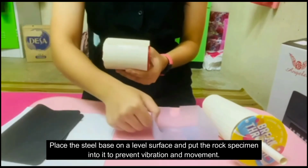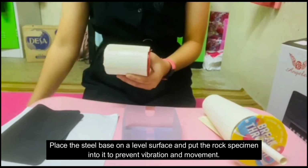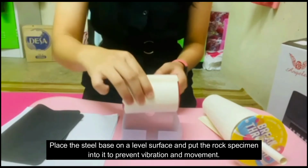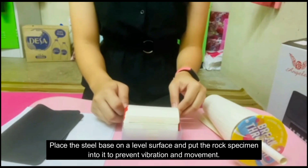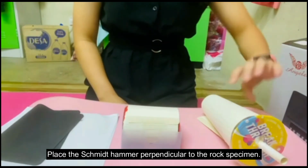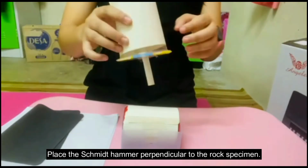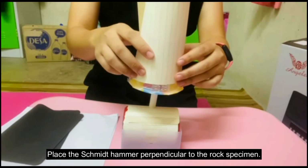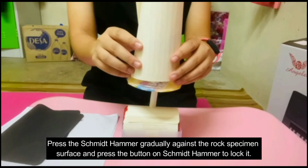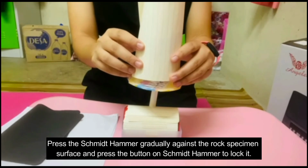Then we place the steel base on a flat and level surface, and we put the rock specimen into the steel base to prevent vibration and movement. Next, we take the Schmidt hammer and place it perpendicular to the surface of the rock specimen. Then we press the Schmidt hammer gradually against the rock specimen surface.